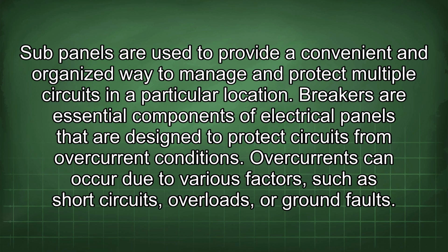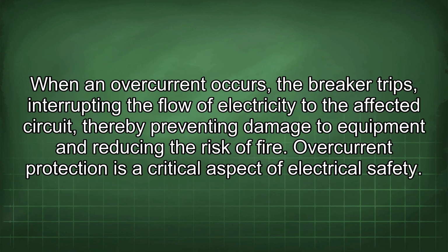Breakers are essential components of electrical panels that are designed to protect circuits from overcurrent conditions. Overcurrents can occur due to various factors, such as short circuits, overloads, or ground faults. When an overcurrent occurs, the breaker trips, interrupting the flow of electricity to the affected circuit, thereby preventing damage to equipment and reducing the risk of fire.